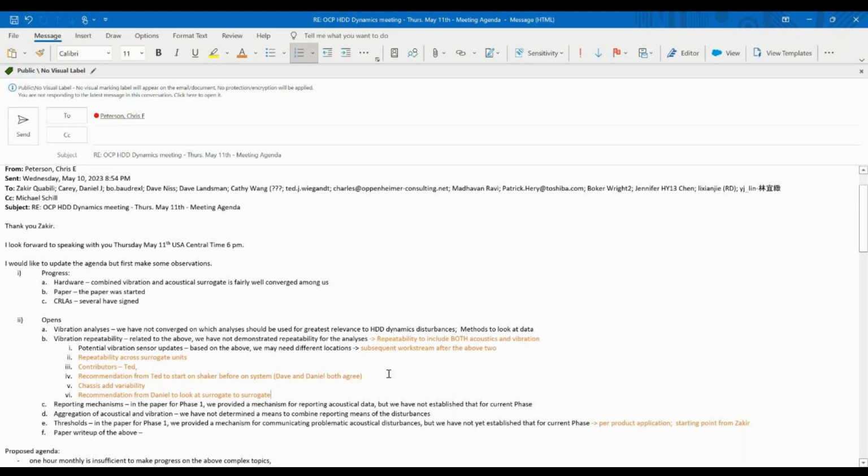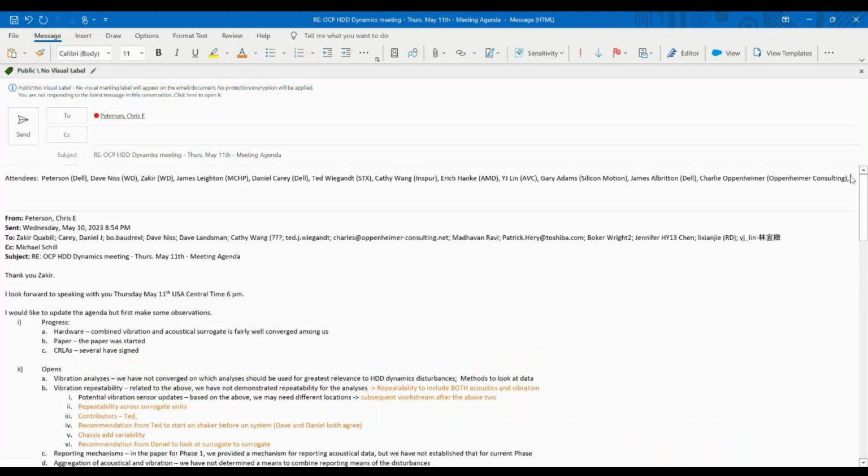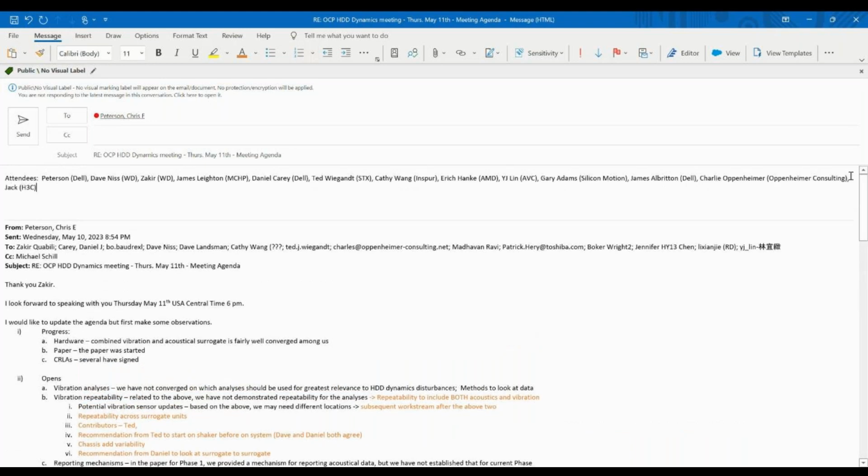I think it's good to look at the surrogate on a shaker, just to say okay, our expected repeatability is within 1 dB, and then to also do it in a system, replacing the carrier, putting the carrier back on, doing everything, completely taken out, put it back in, do that quite a few times, and just get some idea. Because if we're finding that the repeatability is 4 dB, 5 dB, and then we're going to sit there and try and split hairs on a spec, well, we really need to know what essentially the gauge R&R is on that, so that we have some idea going forward. I don't know if it's the time, but I'd like to contribute that we've run some of those studies here, so I have some results I could share already. But we're planning on running a few more.